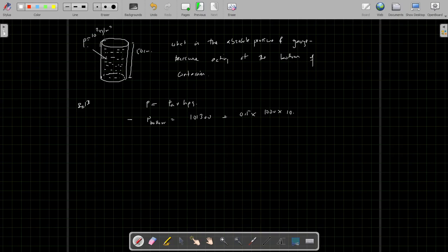I get here 101,300 plus 0.5 into 1000 into 10, that gives me 5000. So 106300 Pascal. This is the absolute pressure that is acting at the bottom of the vessel.